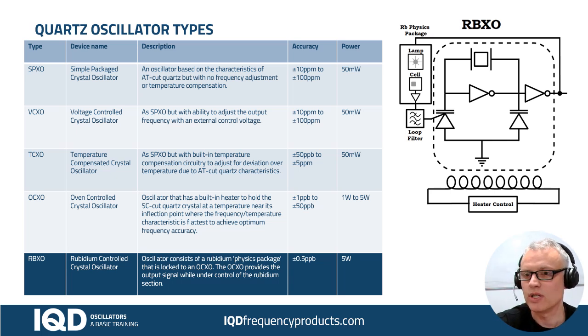With less photons received, we know something's wrong, so we have a system here that then pushes the frequency of the OCXO to build it back up again to correct for that, and so we have a feedback loop that's pushing the frequency of the OCXO as determined by the rubidium gas here.